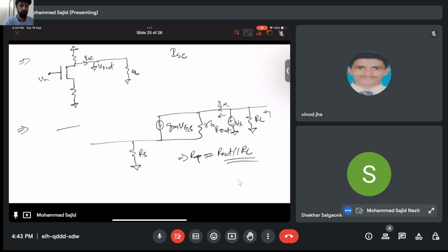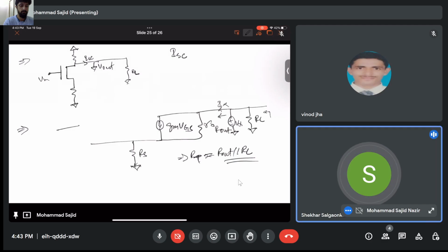Similarly, you can connect here, looking into the source. This boils down to following KCL properly: the node voltage between the two ends of the branch, and what current is flowing in and going out. If you do that properly, you will get the same answers. So is there any circuit where you didn't get the right answer? There are a few. Let me try again.